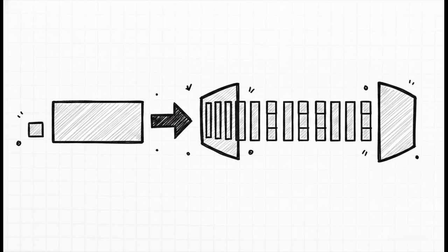If a perfect common centroid is impossible to route just because of the massive size difference of 64 total fingers, use a high-quality interdigitated arrangement while maintaining strict core symmetry. You make sure the reference fingers are nested symmetrically right within the output fingers. And of course, you cap the entire array on both ends with multiple dummy fingers to guarantee identical source and drain environments for every single active unit finger.